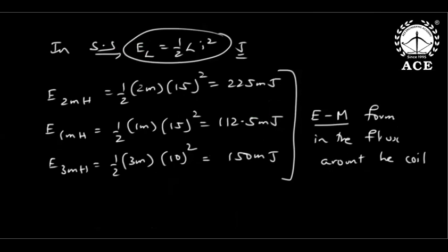See, this opposition will come when there is di by dt. Okay, sir. When there is a rate of change, then induced EMF will occur. However, in steady state, there is no rate of change. The inductor will only retain that energy. This concept clarity you will get tomorrow in the second problem.